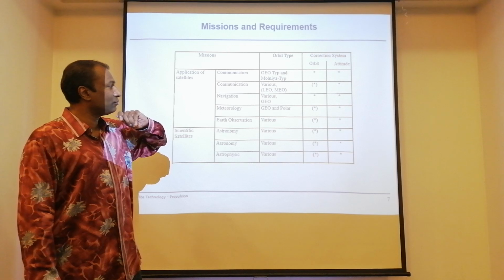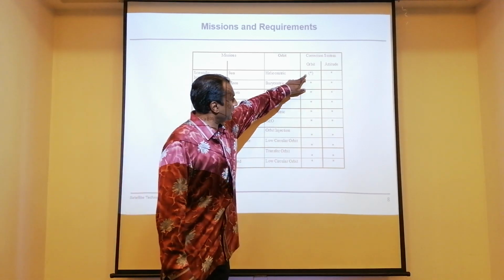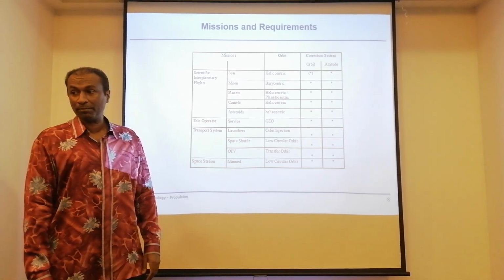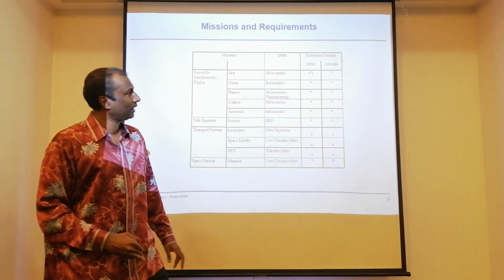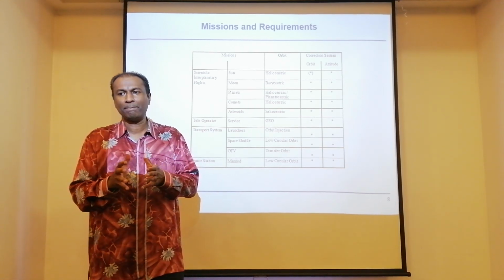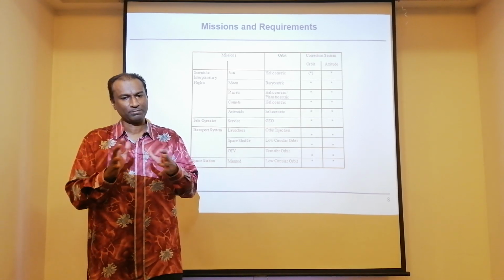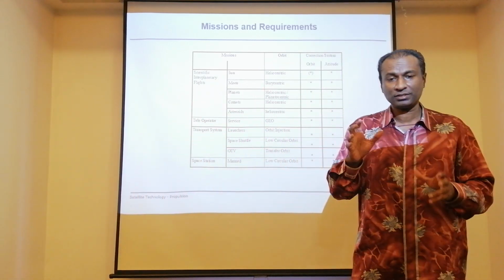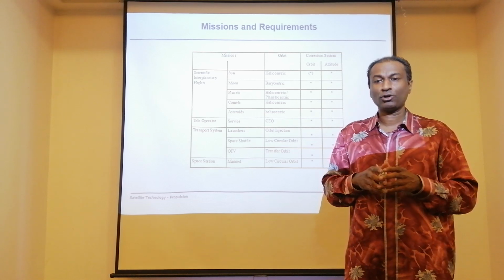On the next page we also have this. Okay, all this basically says that there's an option. Now if you look at it, that means the orbit system or the orbit motion is optional. But the attitude motion, the rotational motion, in any satellite is a must. That means you should have the attitude control system in a satellite. It is mandatory for any satellite. It could be low cost, etc., but rotational motion is mandatory. Translation motion, when it is operating in its orbit, is optional.